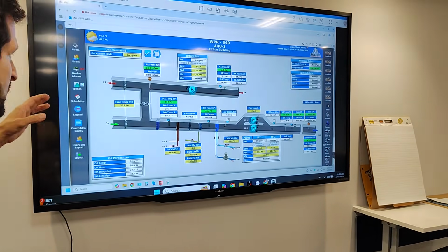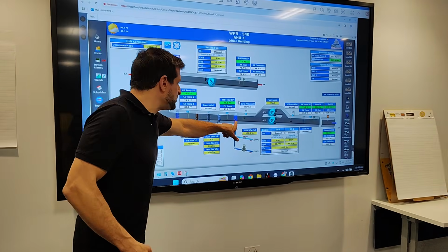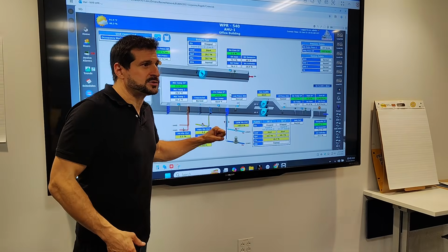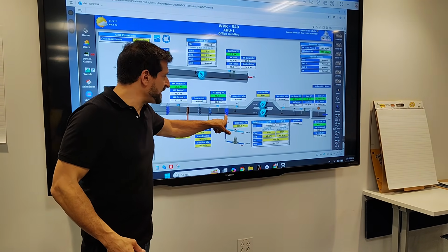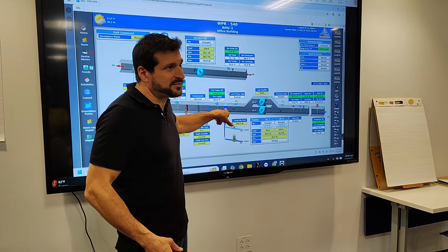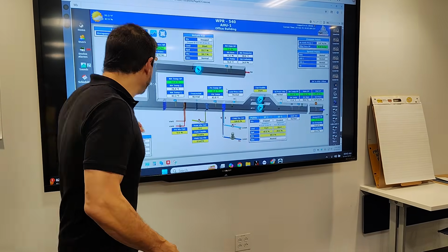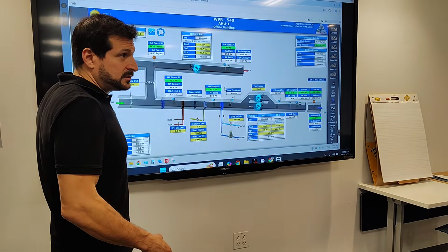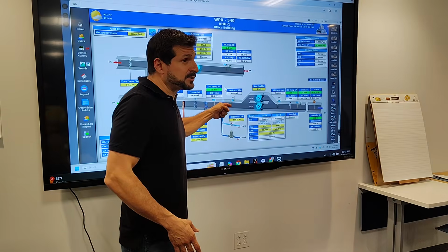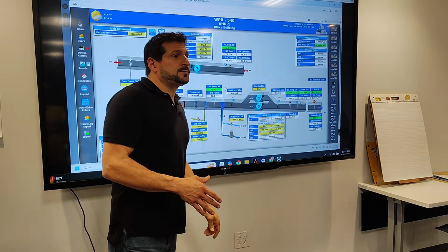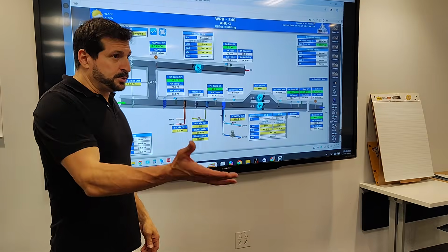But what I'm trying to tell you about, even with this coil here, let's say everything's operating the way it's supposed to operate. Minimally, I should be able to get 25 degrees across that coil. So if it's 80 degrees outside, I should still be able to get to 55 degrees over here. We can put this chiller 2 on. We just got to put water in the cooler. But do you understand what I'm saying?